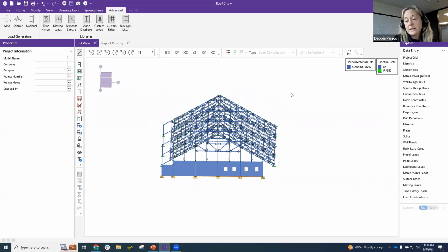That's a floor system. If you want to do the entire floor system, it will calculate the studs and the forces of the composite behavior. But if you have just a single composite beam, a great way to do it is Risa Calc. In Risa Calc, you can just do a component, one single beam, and it will calculate the same stud information, but you don't have to build the whole model. So that's a great single option.